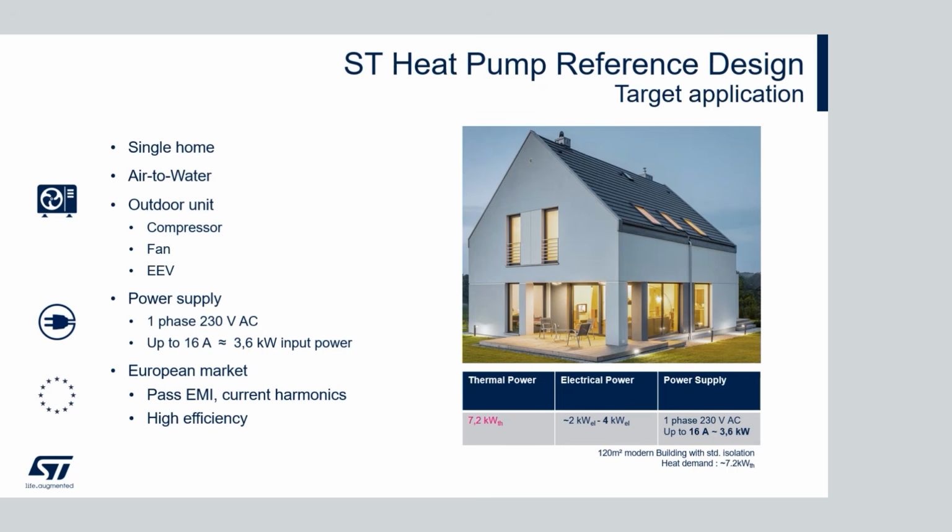And with the current state of the art of heat pumps and their COP, the coefficient of performance, of around 2 to 4 in these calculations, we can say that this would require around 2 to 4 kilowatts of electrical power to provide this amount of heating. So we set out to supply this design with just a single-phase input of 230 volt AC to make it easier. And this would be possible to supply with a 16 amp circuit in a residential home.